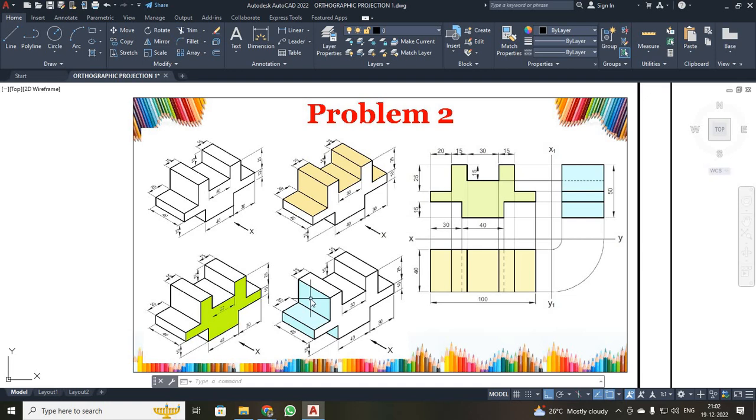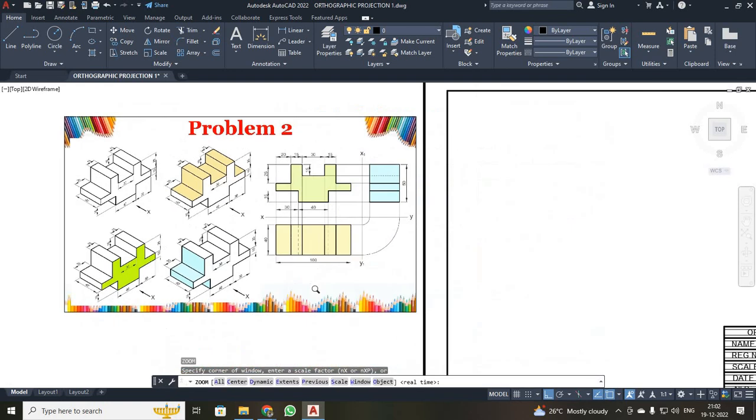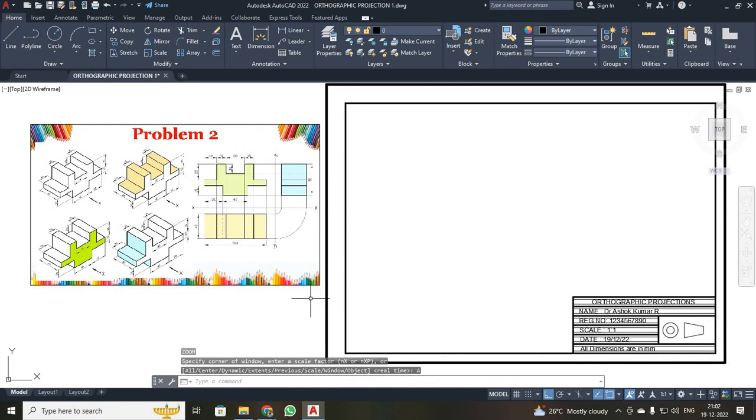Good. Now I am going to start the diagram with the AutoCAD software. We have already discussed how to draw a title block and margins. Whenever you start drawing an orthographic projection, we have to insert a few lines. Normally for the ellipse, parabola and hyperbola, we use only continuous lines, whereas here we have hidden lines and center lines. For that, these two lines should be inserted first.